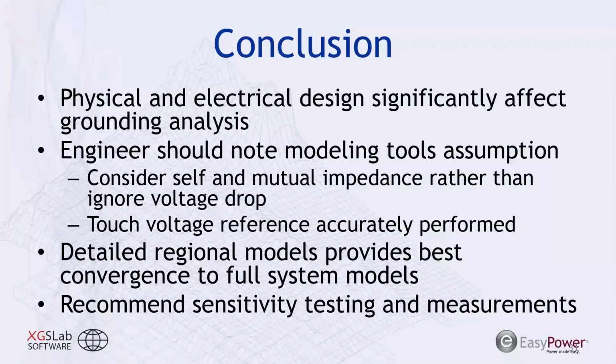With the XGSLab software, you should be able to model pretty much anything. It's mostly going to be your hardware that limits how much of your system you can model. And again, I really recommend sensitivity testing in order to understand how your specific system performs, because the case studies we walked through in this webinar show a specific soil resistivity, a specific fault current, and a specific geometry, and those are all going to play into how your system performs.